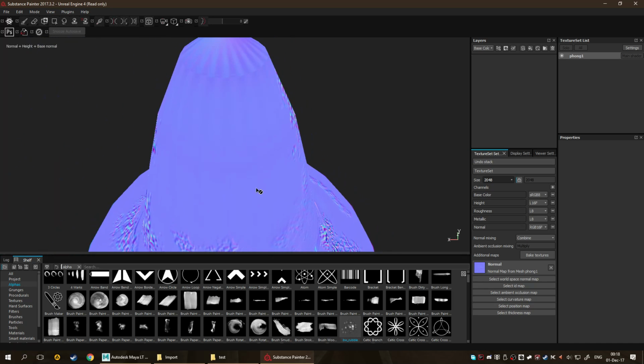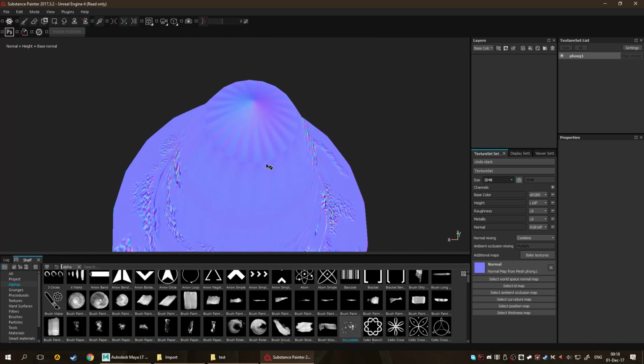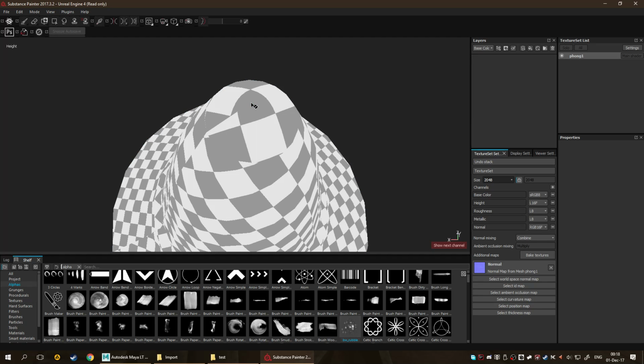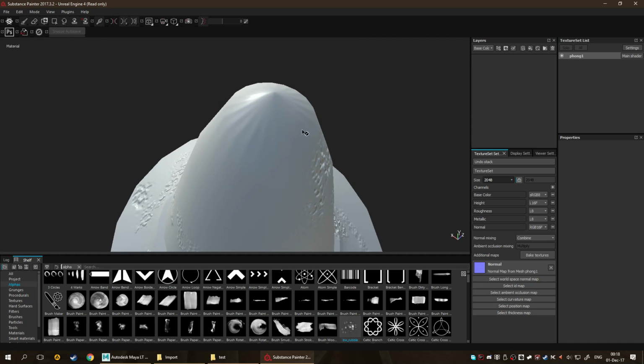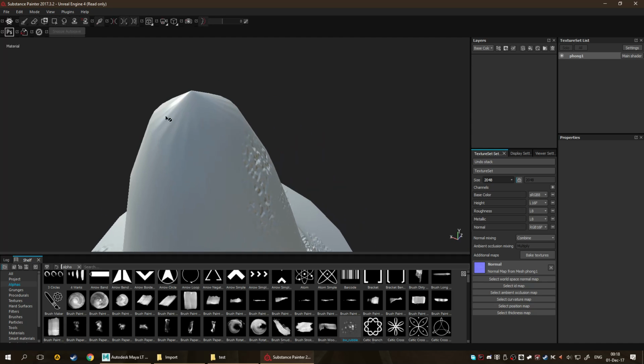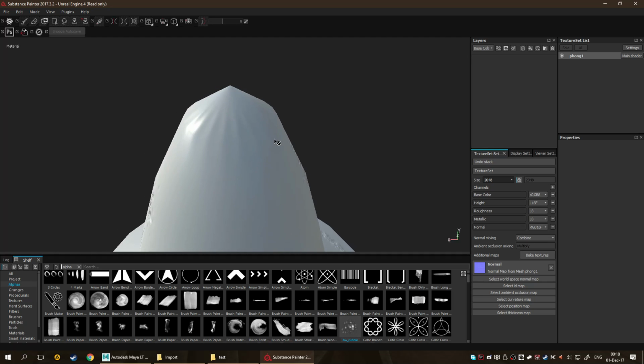But there's one thing that I want to tell you using this normal map: you can modify a normal map. You can paint on top of it, and you can fix some problems that come with it, all right? To further illustrate this, remember, the normal map gives the information on how to calculate the light and what is the apparent visual depth of the object at the given observational angle.